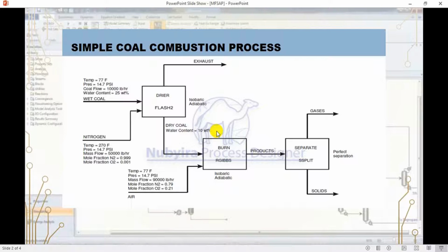But generally what we're doing today is trying to automate the whole process. You don't want to make it manual, where all the parameters in the blocks are specified by hand. So we want to automate it based on flowsheet values using a calculator block.